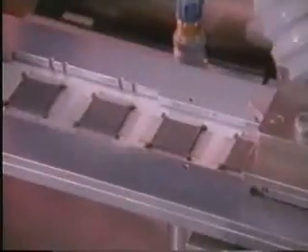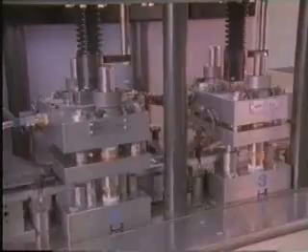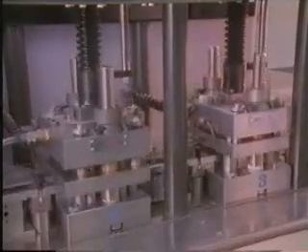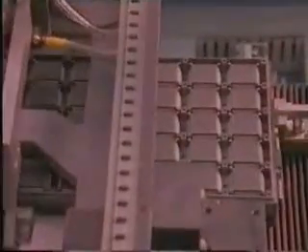In this process, the individual devices are removed from the strips. The leads are cut from the frame on 4 sides and bent into their final configuration. The formed leads are then cut to their final length. The chips are punched out of their frames, and each one is now an individual package.